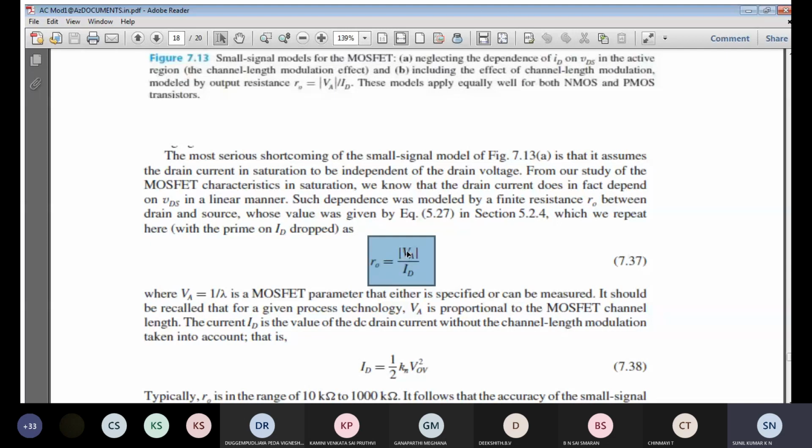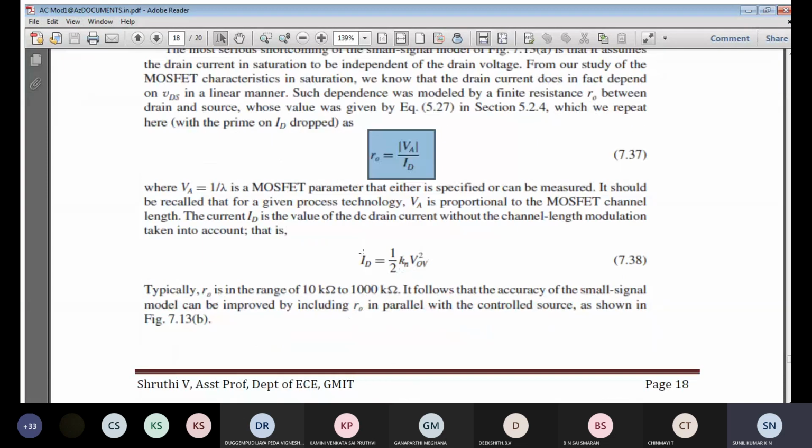At that early voltage point, you get the constant current. VA is written with a modulus symbol because the voltage you get is a negative voltage. Divided by ID, this gives us R naught, the output resistance. Then we can also find out the drain to source condition.